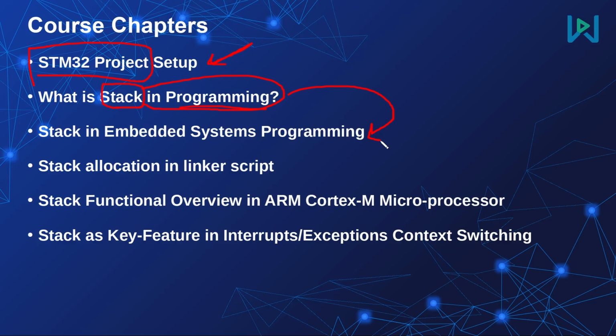Then we'll go to define and get to know how stack is used, especially in embedded system programming. Within the context of embedded systems programming, we'll see how we can allocate stack using the linker script.